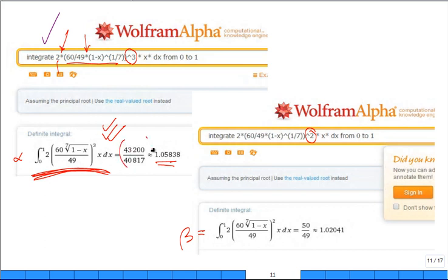It looks like it was able to do it without numerically, you know, doing it by figuring out what rules to apply and then putting in the numbers, and it gets a ratio of numbers. Or if you just want the numeric value, 1.05. In here, it's around 1.02 for beta. It's very close to 1, so often neglected if it's turbulent flow.